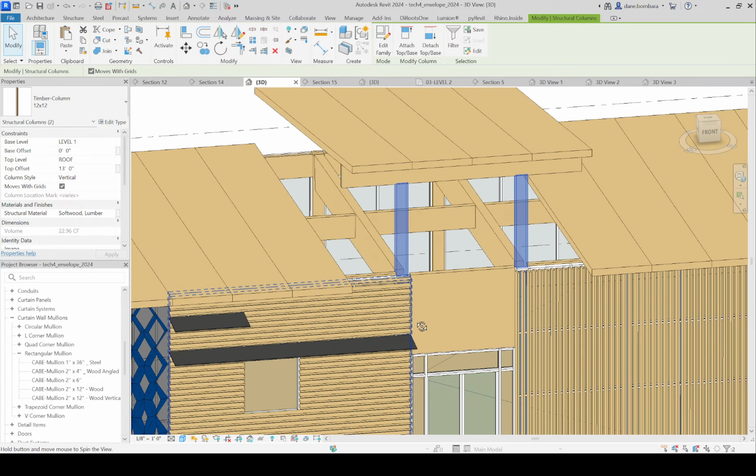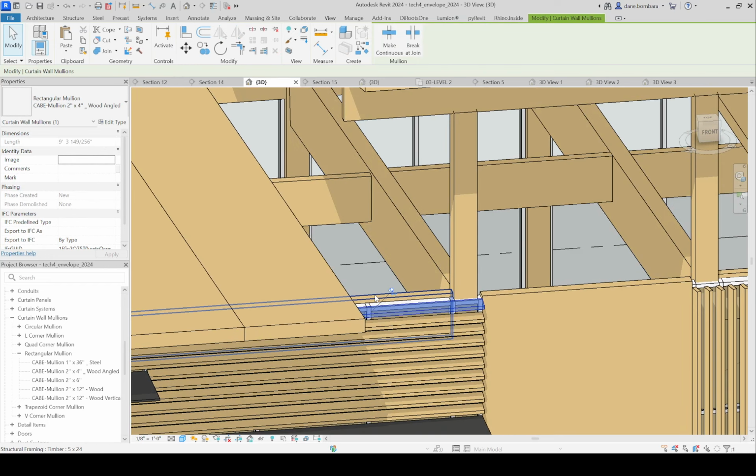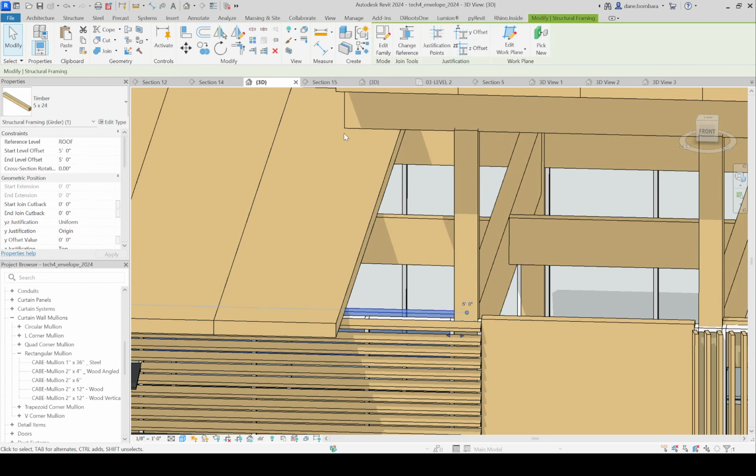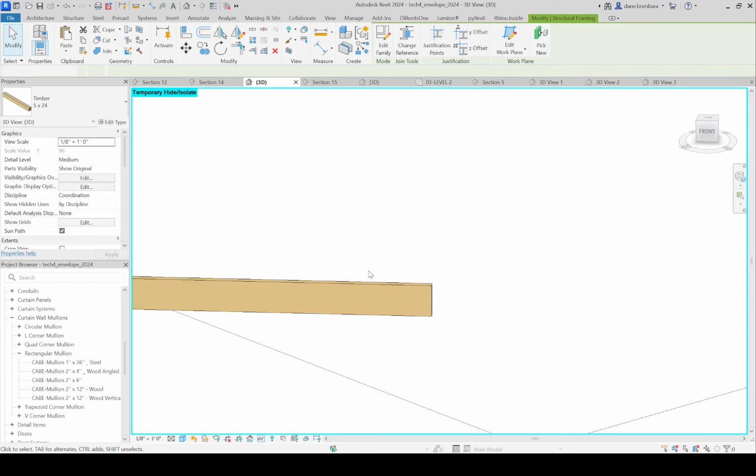There's this way. The other way I thought was, I post another column on top of this beam here. Oops, it's not a beam. There's a beam right there. I do a column that goes up and grabs that end, but then that beam is a point load on that. Or there's a column coming down and it's adding a point load to this beam right here. So then this beam might get deeper to grab that weight, yada, yada, yada, all that fun stuff.